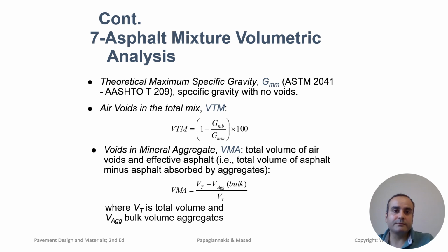The air voids represent the empty spaces in the mixture that are not filled with asphalt binder or aggregate. Air voids represent the volume of air spaces within the compacted asphalt mixture, usually expressed as a percentage of the total volume. Air voids are important because they provide a space for the expansion and contraction of the asphalt due to temperature changes. Proper air void content helps prevent pavement cracking and rutting while allowing the mixture to resist moisture damage.